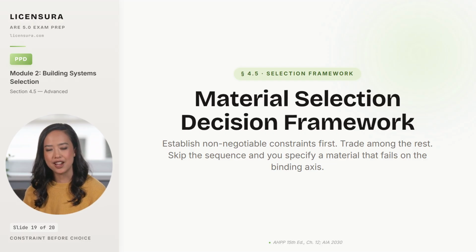The framework that actually works is to establish the non-negotiable constraints first: code-mandated fire rating, structural capacity, exposure conditions, climate compatibility, and only then evaluate the remaining options against the soft criteria like aesthetics, sustainability, and cost. Material selection is a sequence, not a list. The exam will test whether you understand the order.